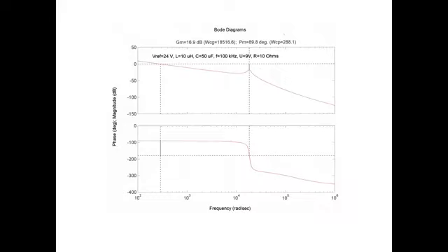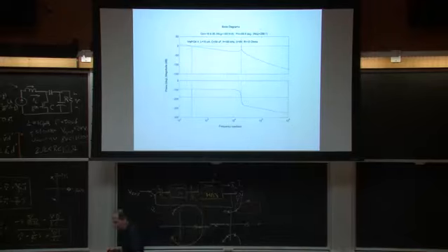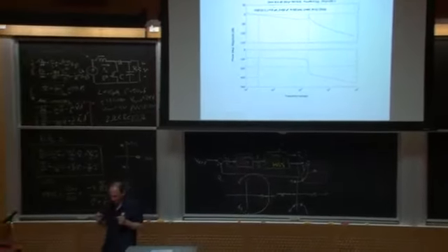And then you have to ask the question, is that tolerable? And maybe I don't care about 30 millivolts of ripple at 20 kilohertz because there's some lightly damped pole pair, right? I could live with that. But there's other applications where they tell you, oh, by the way, you've got to have your output voltage rock solid, and some lightly damped pole pair that's going to get excited by noise and just wobble around is probably not acceptable.